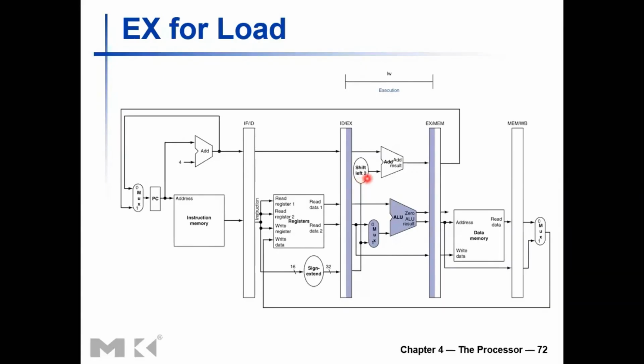You only need to do some rewiring there, so it consumes very little time. Adder consumes some time, but the dominating component here is the ALU. ALU might have a very similar adder there, but it also has some other components which add delays into the data path, like multiplexers. So the ALU is the dominating component here.